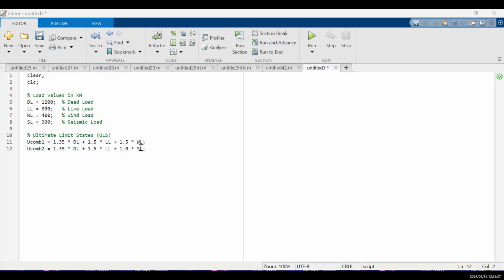This is really important. This is the extreme condition. So for the stability of the house, you have to know how to combine the loads properly. And these numbers that we have here, 1.35 and 1.5, are safety factors, all right?